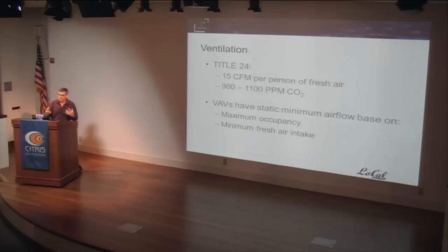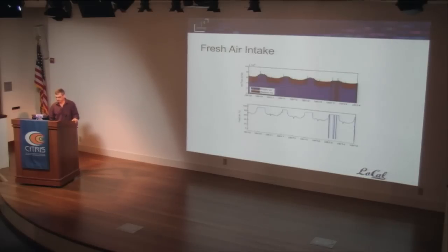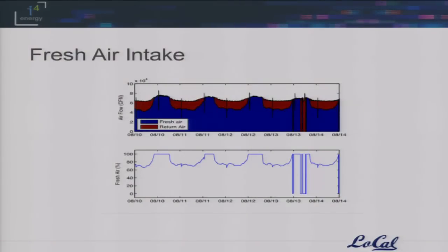So using this kind of ability to really see what's going on inside, we've been able to look at how we pay attention to the actual occupancy when we're determining the amount of fresh air that we're driving, and how we move things back towards a kind of minimum level of delivery for that. And this gives you a little sample of things that you couldn't necessarily do with the infrastructure built into the building. This is saying, let's let the variable air volume unit, whose job it is to deliver a certain amount of fresh air to the occupants, know how much fresh air is coming in through the economizer. And there you can see in the blue the kind of mix. So this is an example of a kind of whole building control that in the future will be typical and today is rather difficult unless the building was wired for that particular substrate.